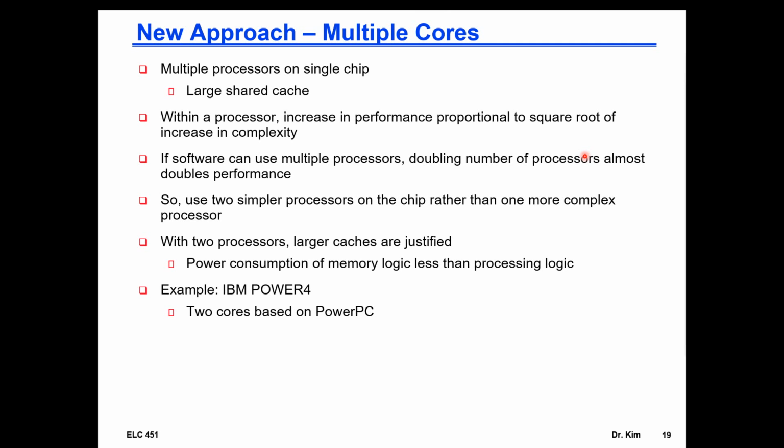But the main reason that we have multi-core processors is because we are not making them faster from a clock rate perspective. Clock rate or frequency is directly proportional to power dissipation. And there was a time where around 3 gigahertz, these chips were getting so hot, beyond 100 watts.